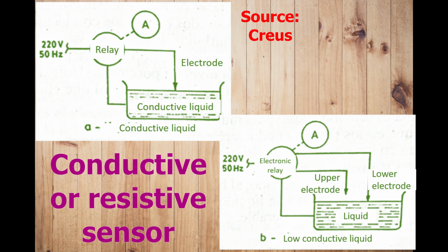For example, in a steam boiler, the instrument is used as high and low level alarm or control, uses electric relays for liquids with good conductivity and electronic relays for liquids with low conductivity. The minimum impedance is 20 megaohms per centimeter, and the supply voltage is alternating to avoid oxidation phenomena on the probes caused by electrolysis. When the liquid wets the electrodes, an electric circuit is closed, providing the electronic relay with a delay timer that prevents its interlocking in the event of a wave of the liquid level or momentary disturbance, or instead, two slightly separated electrodes are arranged electrically interlocked in the circuit.